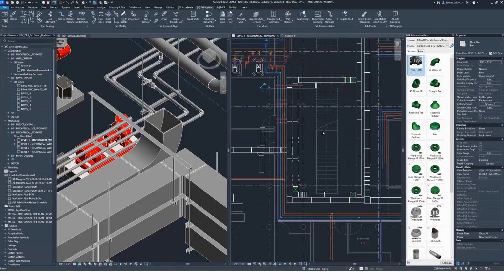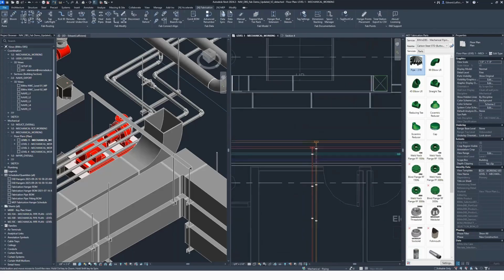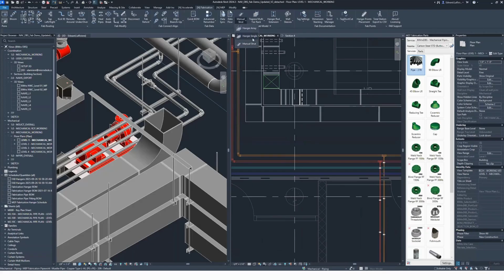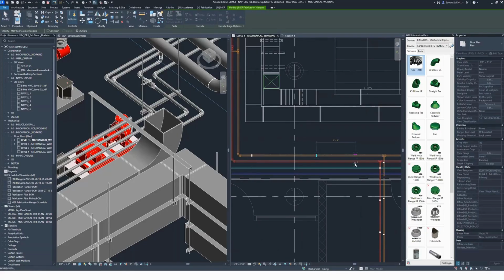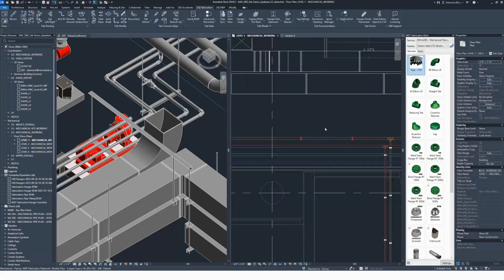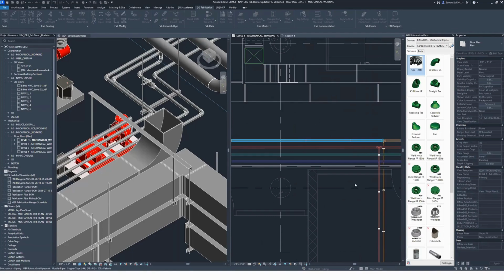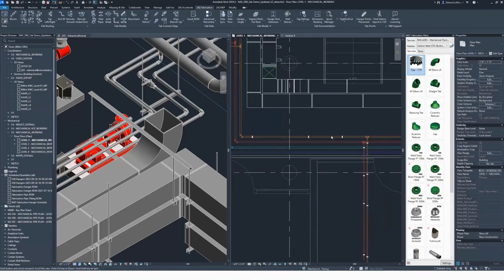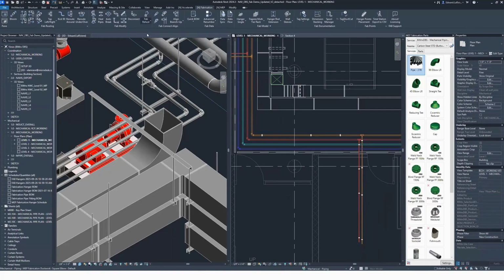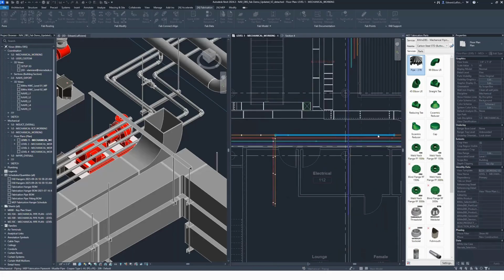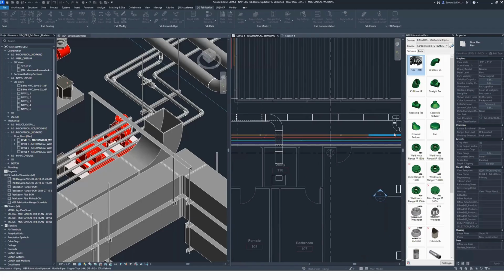Nice and slick stuff. And like I mentioned, we're seeing as we get some of those unhosted ones, they're popping up. If we come down here and think about some of those clevises, maybe you're using something like hanger single to place a couple of them down, but then you got a coworker that forgets, runs through and decides to make a couple copies. Immediately, you can tell that those are not hosted the way they should be. Well, why don't we jump back up and leverage that fab rehost here to go ahead and choose both of those elements and rehost them back down so we're good to go. And then maybe go nudge your coworker and say, hey, buddy, why don't you use that copy rehost instead? And you can just click to place, and we won't need to do that rehost step later. You're good to go.